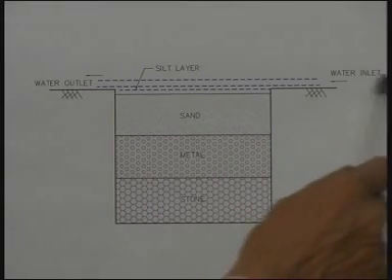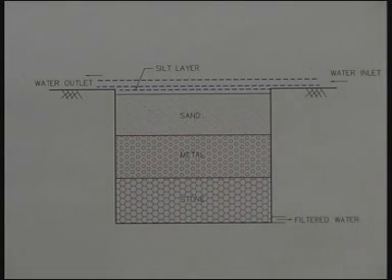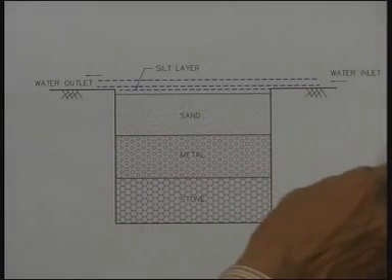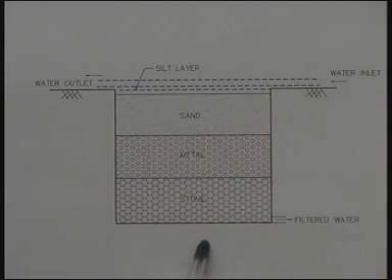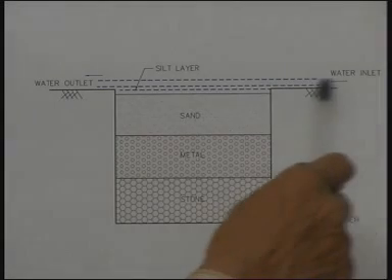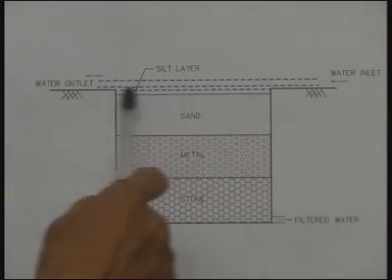Now, the rate of inflow in a 200 square meters plot would be of a dimension varying from 10 liters per second to 20 liters per second. When that is the rate of inflow and the rate of infiltration is so much less, what would happen to the amount of inflow? It finds a way out.